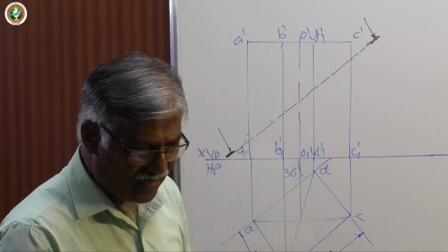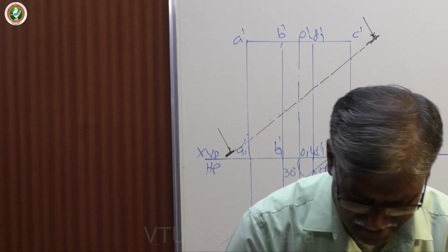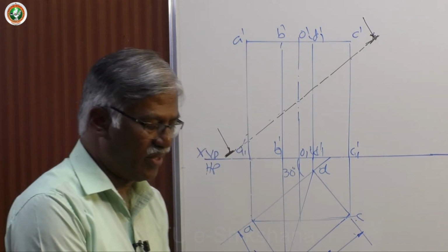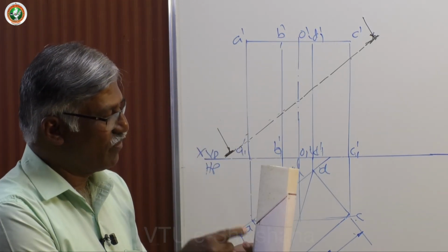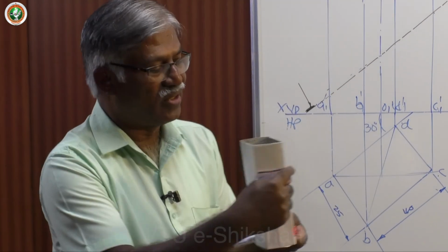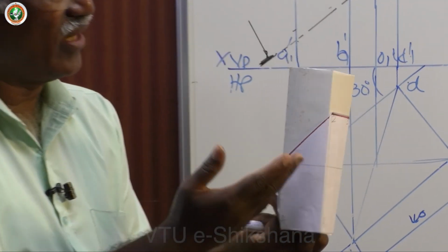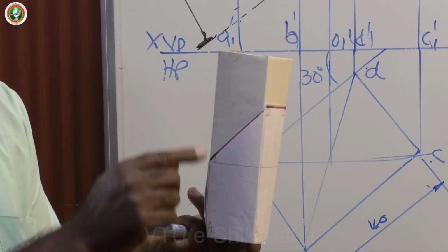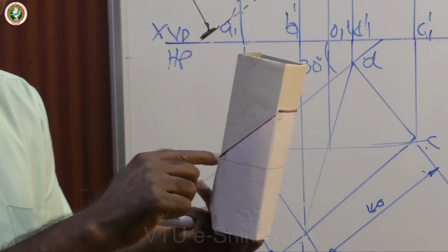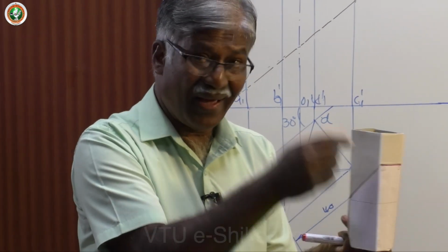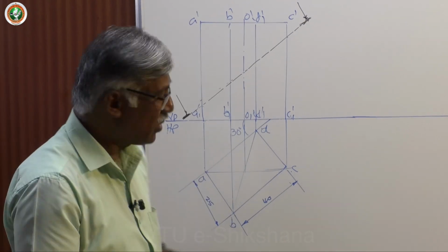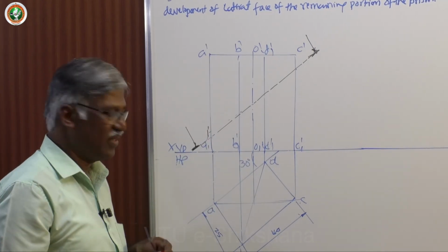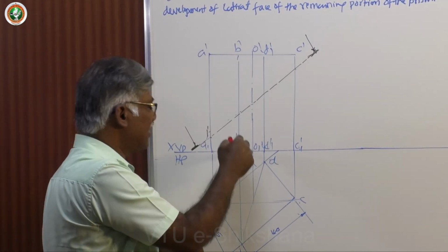So in case of the pyramids and prisms, whatever we have discussed last class, suppose that this is the section plane for a square prism. What we did, assume that this is the second plane, this is the intersection plane, 1, 2, 3, 4. This is the portion to be removed after taking section, this only is retained. This is 1. This is intersecting the longer edge AA1 at 1, longer edge BB1 at 2. Like that, only we have to work here. So, AA1 is intersecting at point 1 dash, I say here. BB1 is intersecting at point 2.